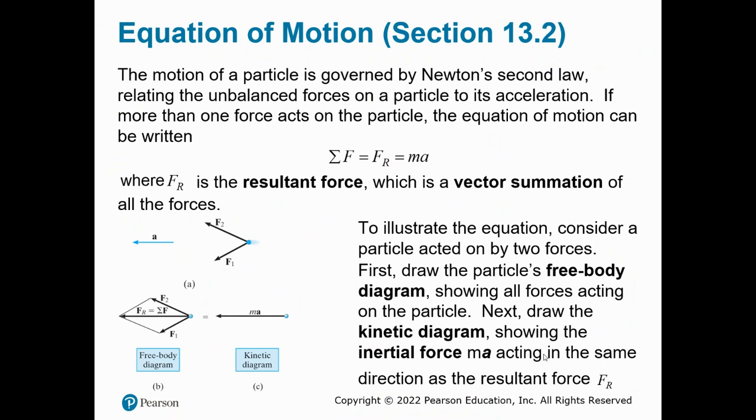First, draw the particle's free body diagram showing all the forces on the particle. And next, we're going to draw the kinetic diagram showing the inertial force ma acting in the same direction as the resultant force. So in other words, you have two diagrams here.